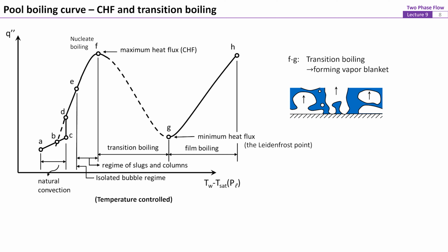The size and the time duration of vapor films right above the hot surface increase significantly in this section. This greatly reduces the overall heat transfer from the solid surface to the surrounding fluid. Finally, the entire solid surface is covered by a stable and continuous vapor film, and the condition of film boiling begins. The point corresponding to the minimum heat flux is called the Leidenfrost point.